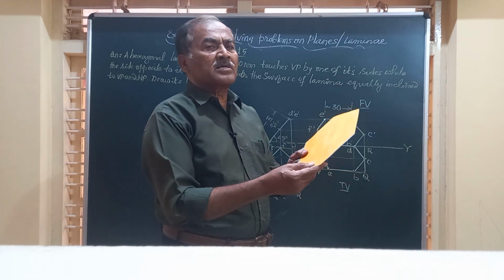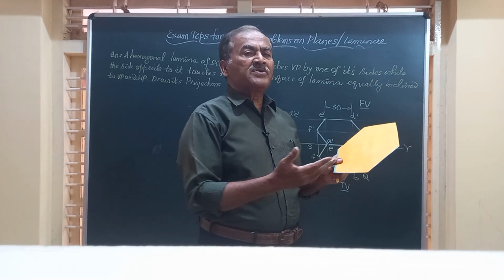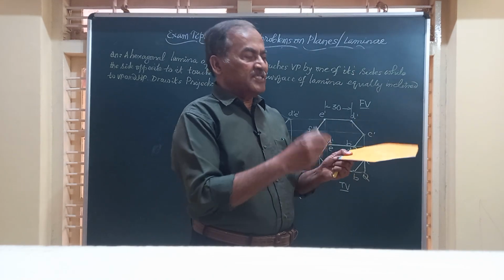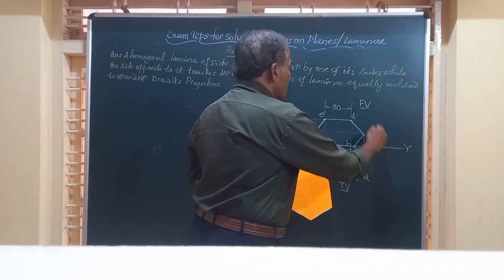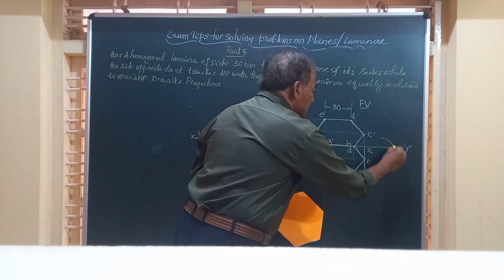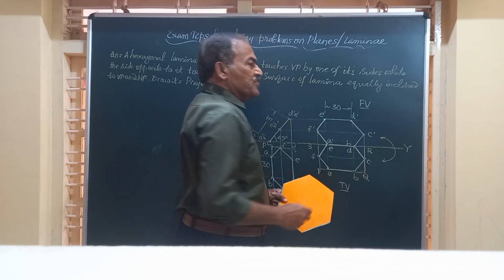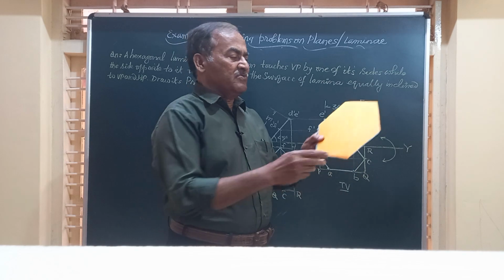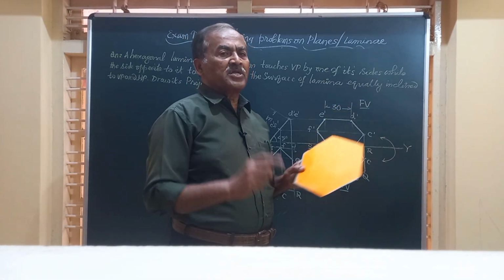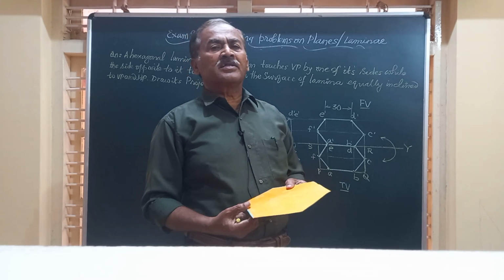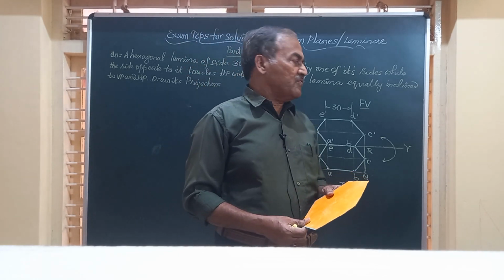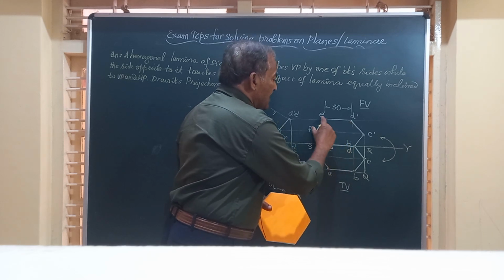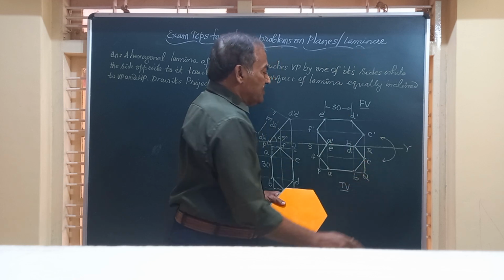So in a figure having an even number of sides, if it is making equal inclination with HP and VP, for example, particularly in this case, whatever front view you have got is exactly identical to that of the top view. The front view and top view will have the same measurements. That is the case when the surface of the lamina is equally inclined to the reference planes, namely VP and HP. So friends, if you measure any of these dimensions, suppose ED equal to this value and this value is equal to this, all will tally.